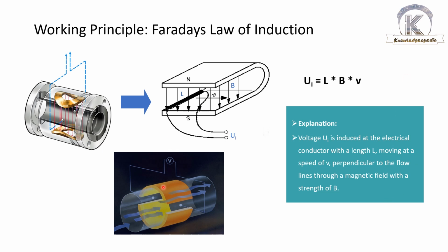So what would be the unit of velocity? It should be something around meter per second, right? And what would be the cross-sectional area? That is pi d square by 4, and the unit will come up as meter square. If you multiply that meter square with meter per second, it comes up as meter cube per second, that is volume flow.